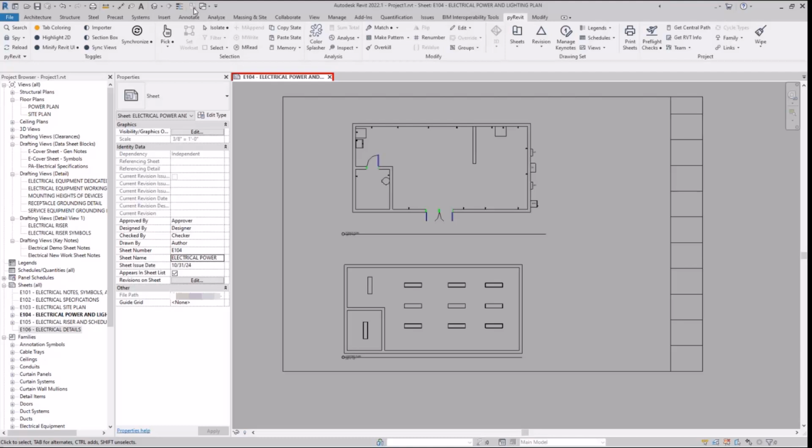I'm not saying this comes up a lot, but sometimes, as much as your overall plan is put a certain way on the sheet and your north arrow is up, that doesn't necessarily mean that when you get enlarged plans or smaller plans they're going to be in the same direction. So make sure you're not just copying north arrows and not paying attention to whether they're actually pointing in the right direction, because they don't always apply the same.